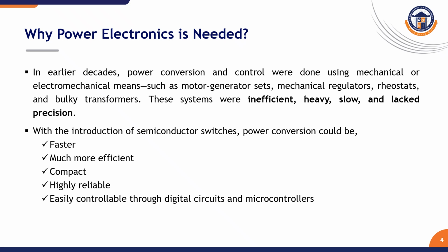So why is power electronics needed? In order to have fast, more efficient, compact, highly reliable and easily controllable circuits with digital circuits and microcontrollers, we are in need of controlled semiconductor switches for power conversions. This gives highly efficient power conversion, because in earlier days we were using motor generator sets, mechanical regulators and rheostats, which are bulky and have more losses. In order to remove those losses, we prefer power semiconductor switches, which give power electronic circuits. These are more compact, more efficient, and faster in working.